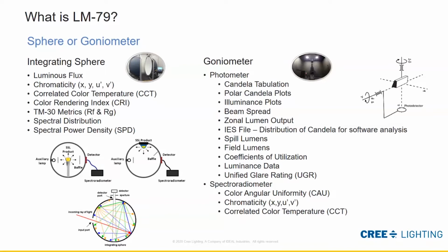But in general, that type of color measurement takes hours, upwards of 8 hours, to measure that much data. So in general, the most common use is getting color and total luminous flux and that data from the integrating sphere, which might take 45 minutes to an hour for a measurement. And then on the goniometer, using just the photometer, getting intensity only, that takes maybe an hour to 2 hours, depending on how long it takes to stabilize the unit.